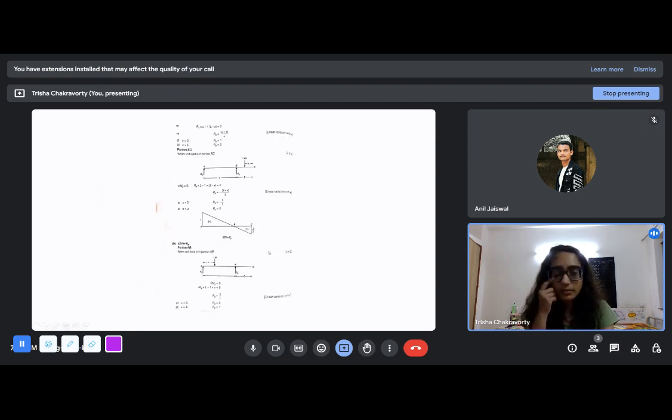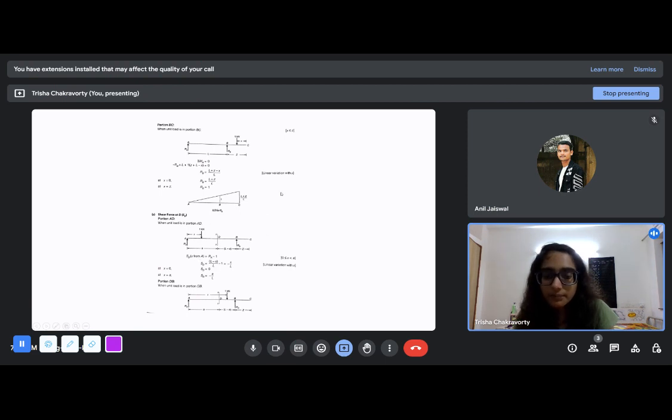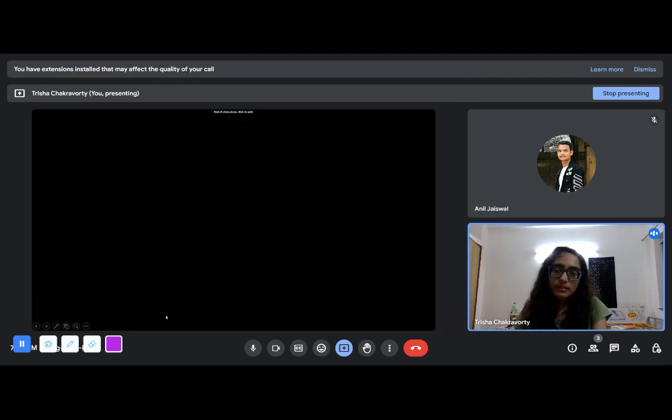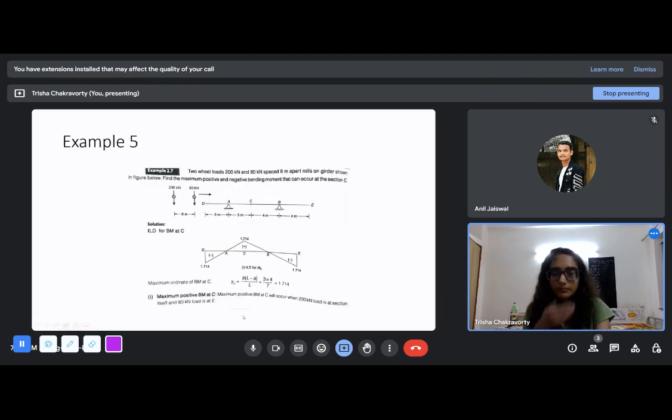And if you look at the bending moment at this section, it rises, it falls, and then it goes negative using the same slope and ends up here. And if there's another overhang, it will be a similar thing. You have to extend this. So L minus A by L will remain constant as in the simply supported beam, and you just have to extend these parts to the ends. So this is what we actually get here.